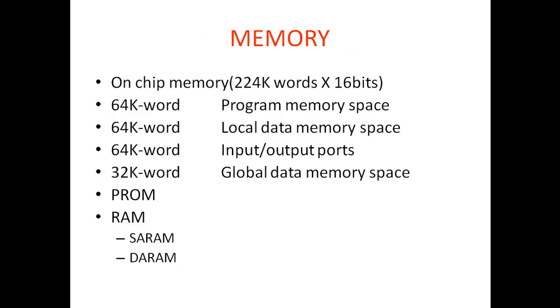On-chip memories of 224 kilo word length of 16-bit length: 64 kilo word of program memory space, 64 kilo word of local data memory space, 64 kilo word of input output port, and 32 kilo word of global data memory space.